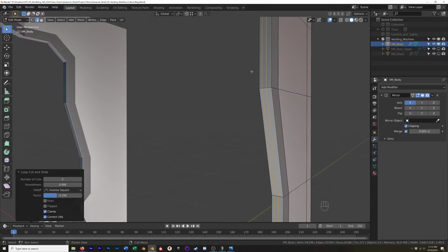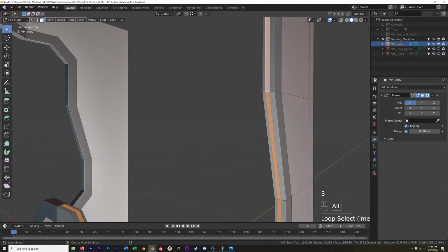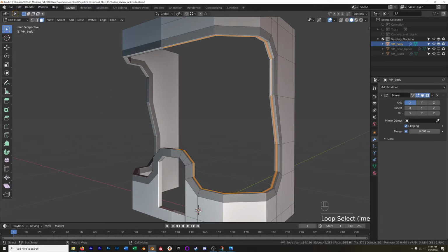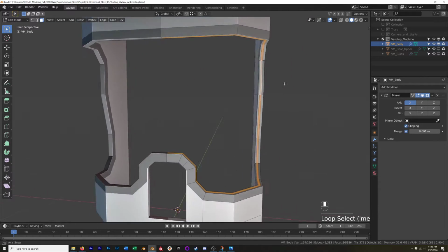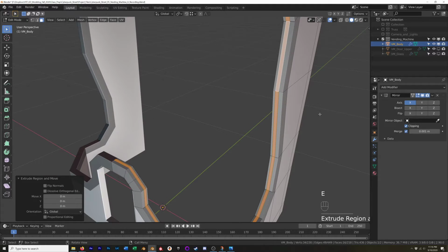It does not make any practical difference. But once I have that selected, I'm going to go and select that face loop. Which again is Alt click on this edge and it'll select the whole loop. Right? Then I'm going to do the same thing that I did to extrude the whole thing. I'm going to hit E to extrude, right click to keep it in place, and then